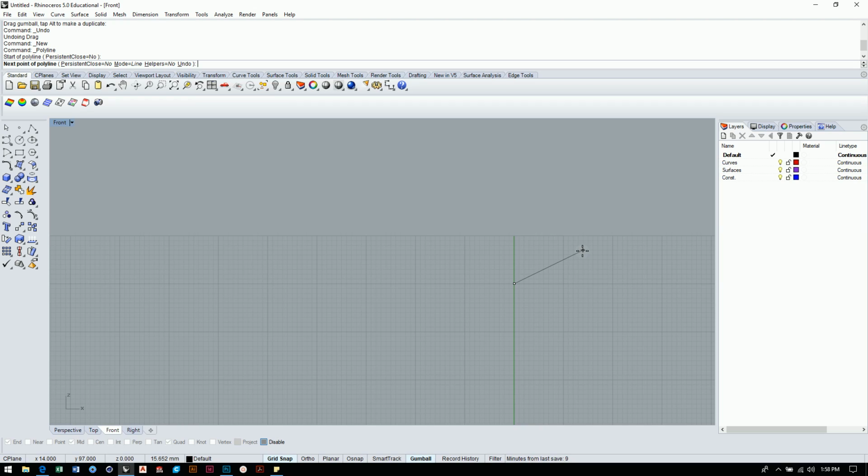And then I'm going to move over to the left, and I've taken a measurement that's 58.85 as the entire diameter of the top of this water bottle. So up here at the command line, I'm going to type in 58.85 divided by 2, okay? And that's going to give me the dimension I need, okay? So I can just kind of click anywhere.